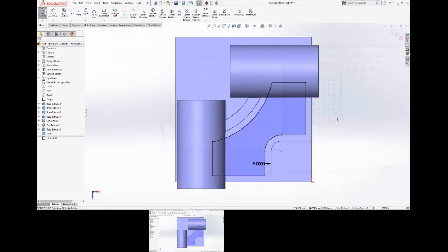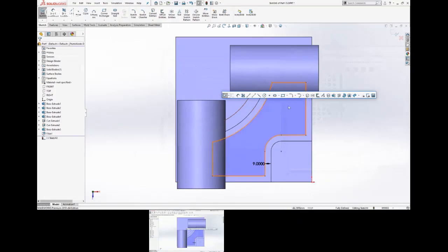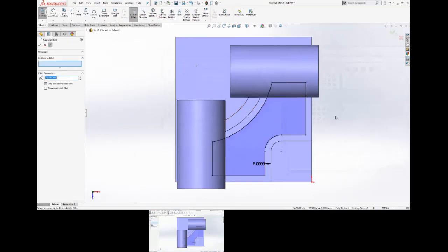All right, so we've got our sketch geometry on there. We need to add the 10mm fillets. So again, hitting the S key, I'm going to grab my fillet tool. Now on here, I want to select these in a purposeful way, right? The very last point that I select for a fillet is going to be where it adds the dimension.